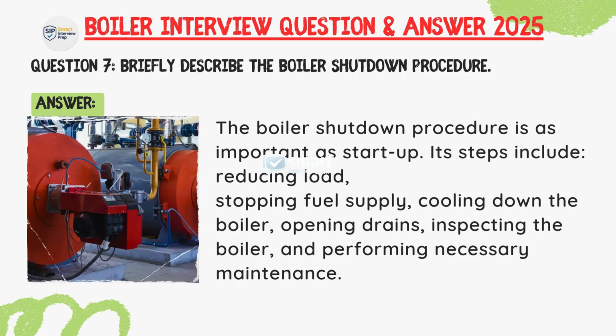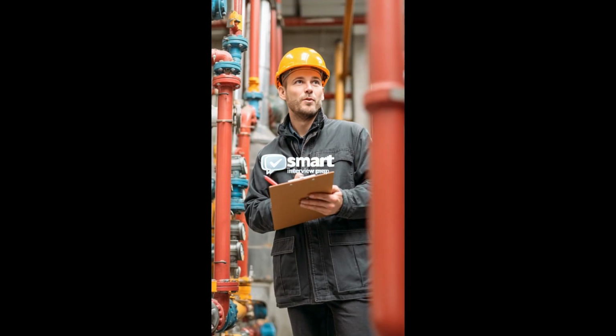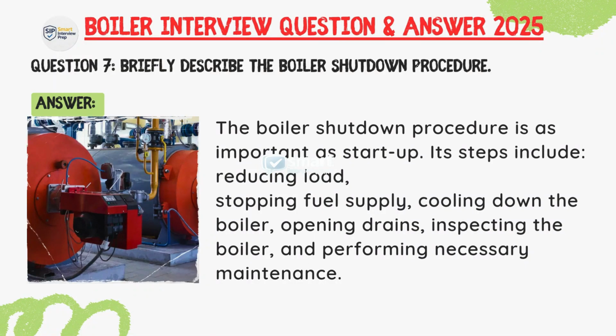Question: briefly describe the boiler shutdown procedure. Answer: the boiler shutdown procedure is as important as startup. Each step includes reducing load, stopping fuel supply, cooling down the boiler, opening drain, inspecting the boiler, and performing necessary maintenance.